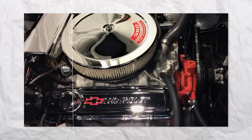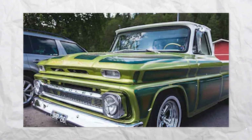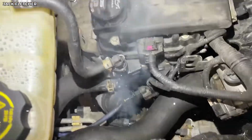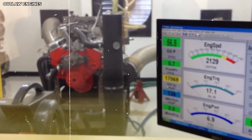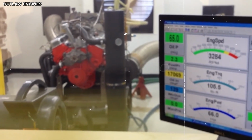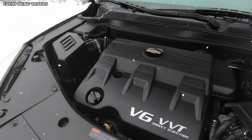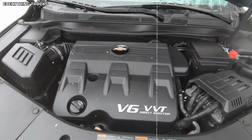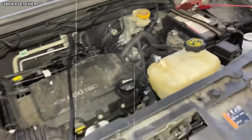After 30 minutes to an hour, reconnect the negative battery terminal and tighten the 10mm bolt securely. Make sure the connection is tight. A loose battery connection can cause all kinds of electrical problems and check engine lights. Now, start the vehicle without touching any accessories. No radio, no climate control, no power windows. Just start it and let it idle for about 2 minutes.